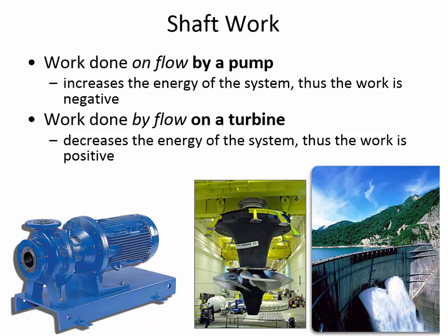More commonly, what we'll be dealing with in hydraulic engineering is looking at pumps and turbines. Shaft work is when you're considering either the work done on the flow by a pump, which adds energy to the system. That's why it's on the left side of the energy equation that we've seen so far. Or the shaft work that's done by the flow on a turbine. That's when we're trying to extract energy from the system, and it's on the right-hand side of the energy equation because it's removing the energy that was at 1 as the water flows towards 2.